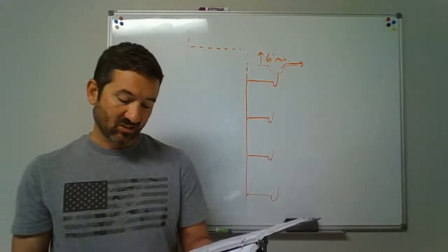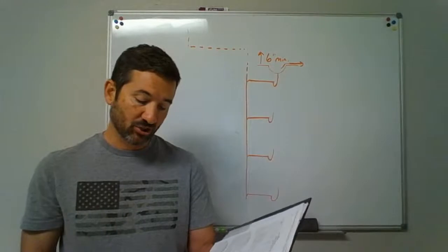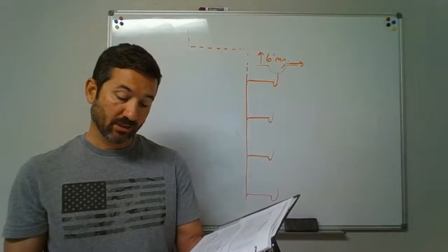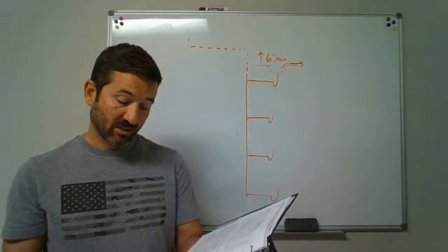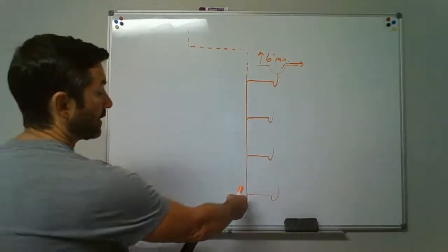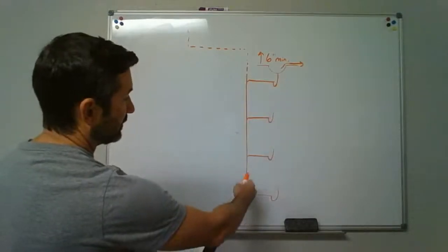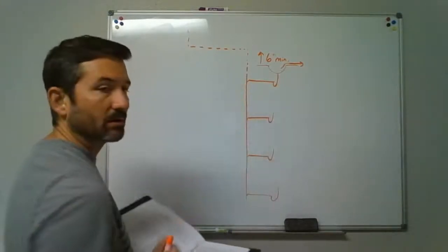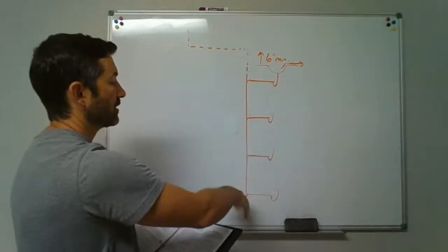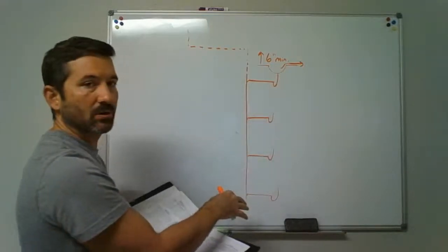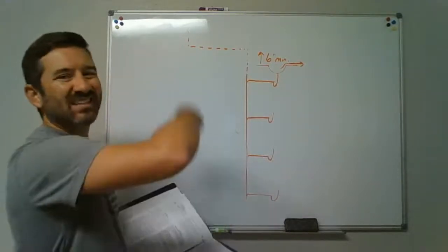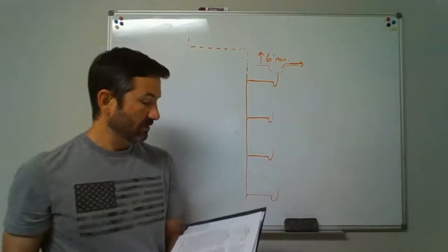913.4 gets into waste stack sizes. It should be sized based on the total discharge to the stack and the discharge within a branch interval in accordance with table 913.4. The waste stack size should be the same size throughout the length. So we can't say, well, it needs to be bigger down here because it's got more coming through, but as we get up, we can go smaller and smaller. No, we're trying to use this whole stack as it's permitted. It's trying to vent everything else. So we're going to calculate the maximum number. How many DFUs do we have on it? We're going to say, okay, this is the size it's got to be, and we're going to run the same size all the way up. I'm not going to reduce it down.